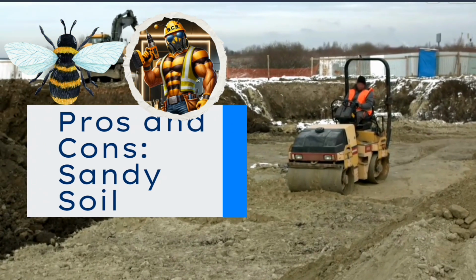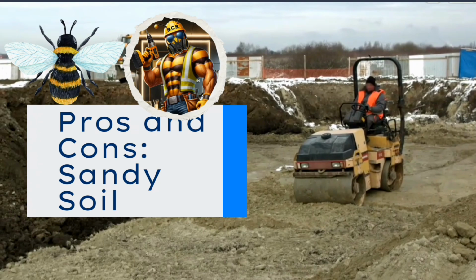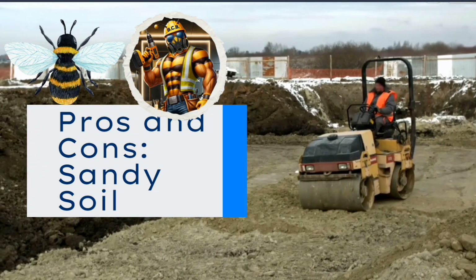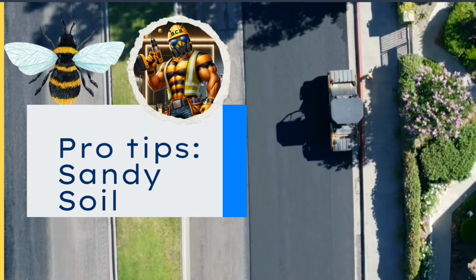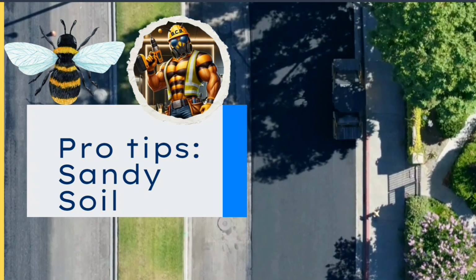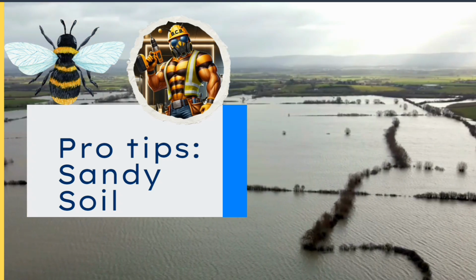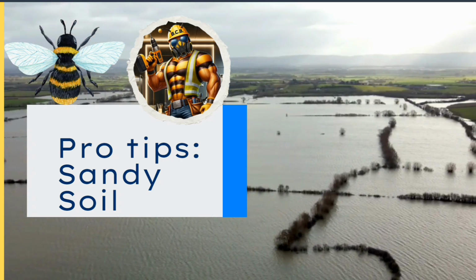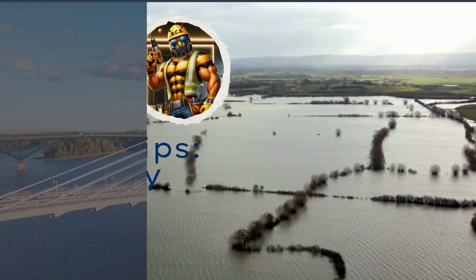The pros of sandy soil are its stability after compaction and high drainage. On the con side, you may need additional effort for proper soil stabilization. For sandy soils, it's essential to use compaction techniques such as vibratory rollers or dynamic compaction methods to increase the soil's load-bearing capacity. In areas with very loose sand, consider adding geotextiles for extra stabilization.